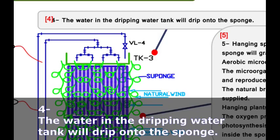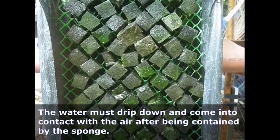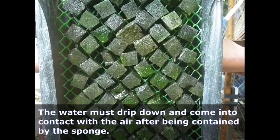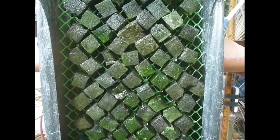Section 4. The water in the dripping water tank will drip onto the sponge. Section 5. The hanging sponge is filled with water. Oxygen is supplied to the microorganisms living in the sponge when the sponge is exposed to natural wind. The water must drip down and come into contact with the air after being contained by the sponge.